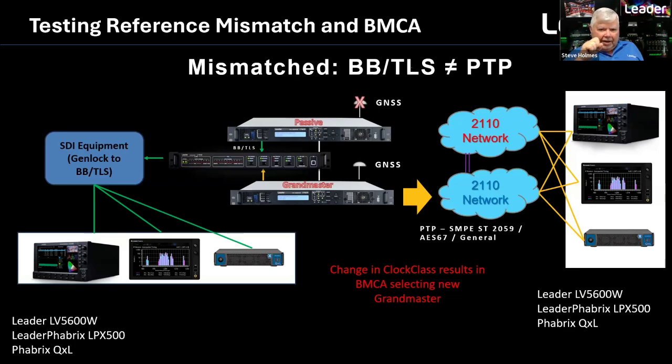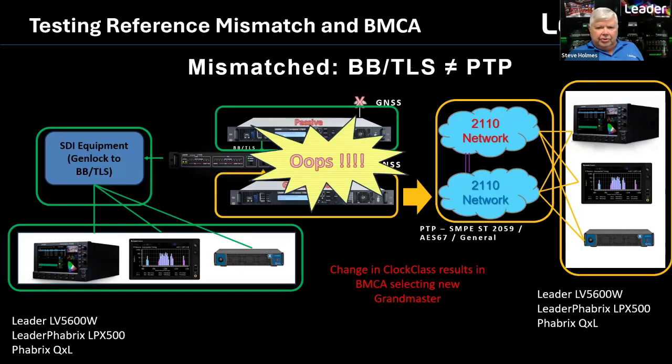And quite often they'll go in and grab that top generator and take it out of service, which is now going to cause a hard fault to all your baseband signals, and everything is going to take a hit when he tears that generator down, and the ECO then finally switches over to the other grandmaster. And what you end up doing is you have this scenario where you've got part of your system running on two different sync generators, which is a maintenance nightmare as well as just a timing nightmare.